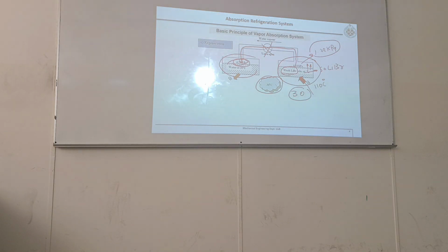In this system, there is a compressor. Whatever water will evaporate, the compressor will take it away and raise its temperature and pressure. Here, whatever water was evaporated, it was absorbed here, and then we supply heat to raise its temperature and pressure. Our input is Q evaporation. Yes, the overall input here is this heat which we are supplying. Our output is Q cooling, which was the second step.